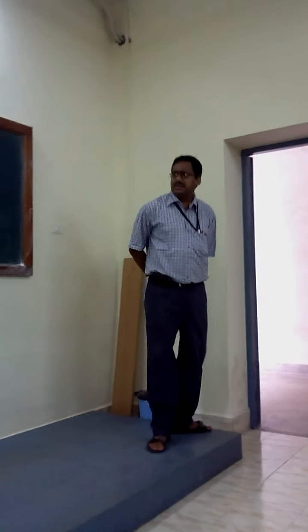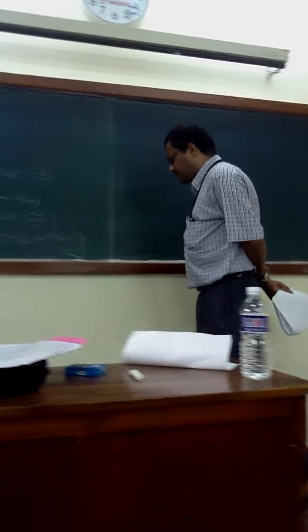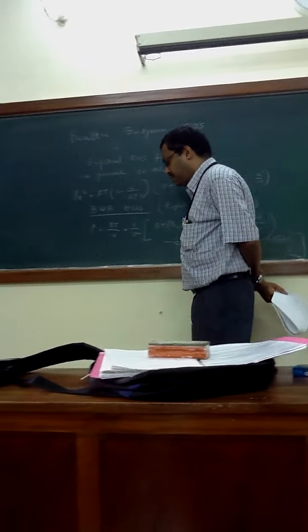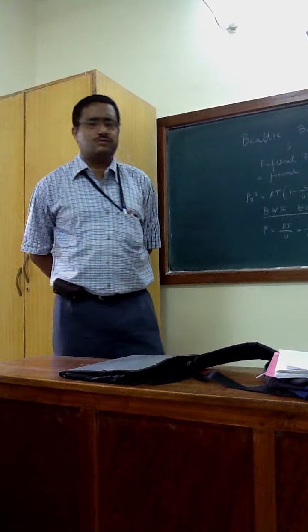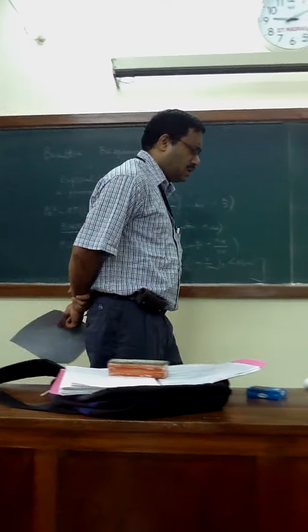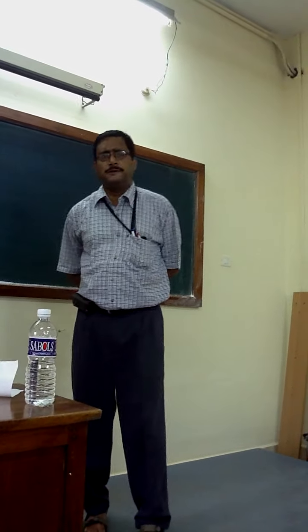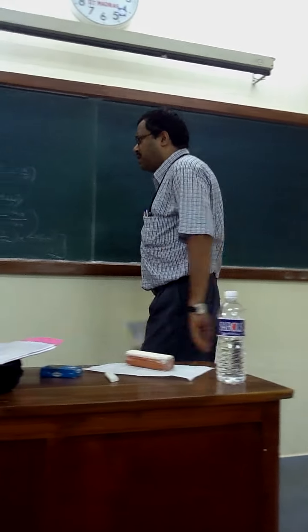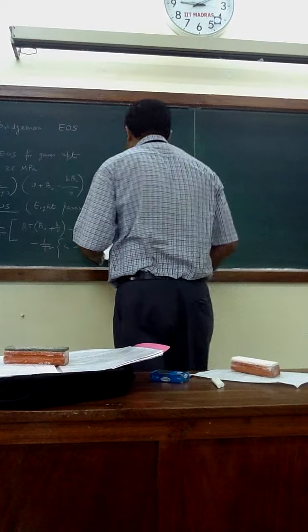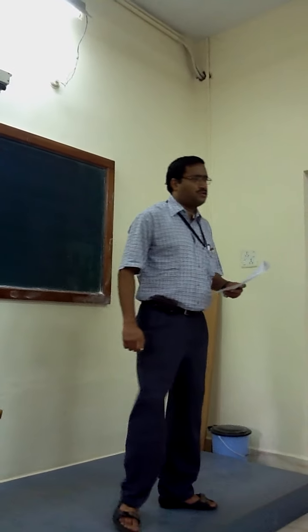So these equations, this second class, what we have done, the first class equation of state as a cubic equation of state, and for those equations of state, it is possible to have a compressibility factor chart. And the same thing in the compressibility factor chart you can actually look into for this second class equation of state, and those forms are called the virial equation of state.